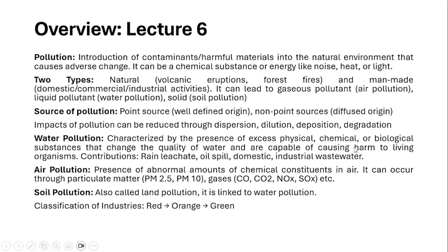And coming to the chemicals, these include surfactants and detergents, which have a large amount of anions and cations. So chemically they are going to affect the water. The pH or turbidity of the water can get increased or decreased based upon the pollutant. And now the biological substances here are BOD and COD.